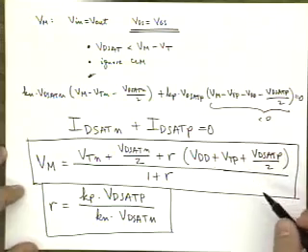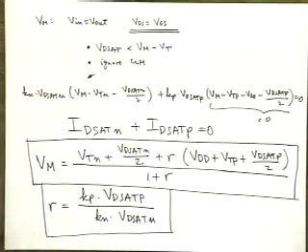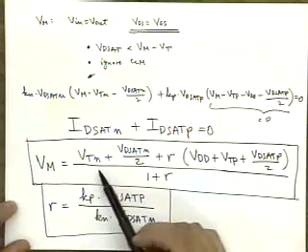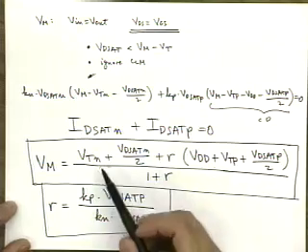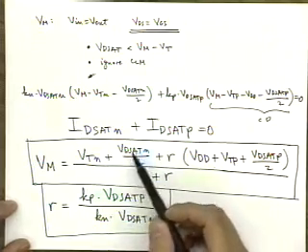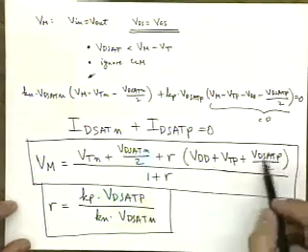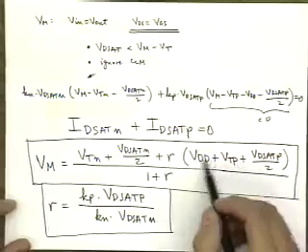Now the question is, how do you control this switching threshold? What does it depend on? When you look at this expression, your process parameters are present here. VTN is a property of your NMOS, a constant that's given to you. Then for PMOS, VD sat is constant, threshold is constant, VDD is constant.